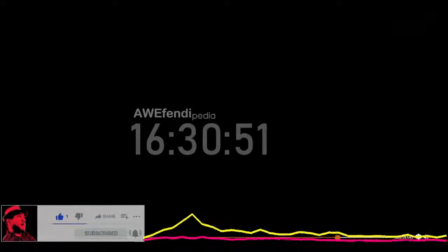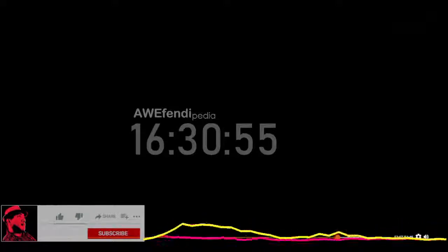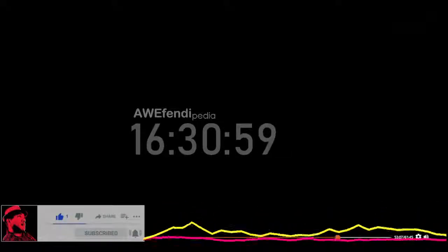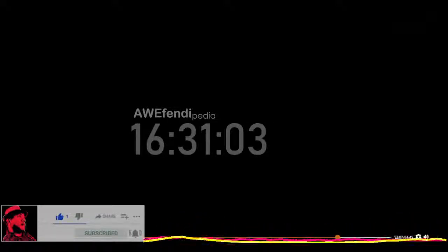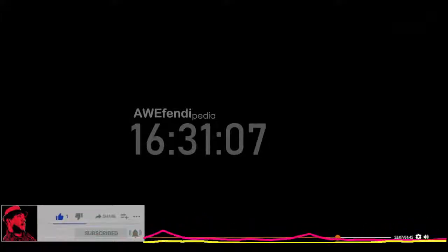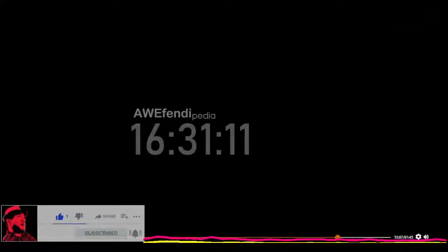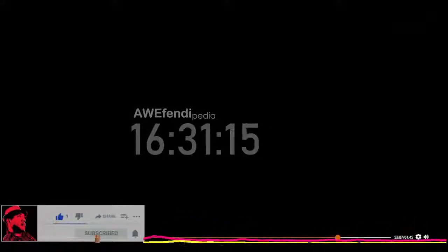If I hover over the element itself, I can see it was actually coded as a bridge abutment. So it looks like this is just a miscoded line. And again, I'm just going to click on that. I'm going to choose quick properties maybe on that and change the field code to a bridge pier, which is BRGP instead of BRGA. And as soon as I make that change, it's no longer triangulated.